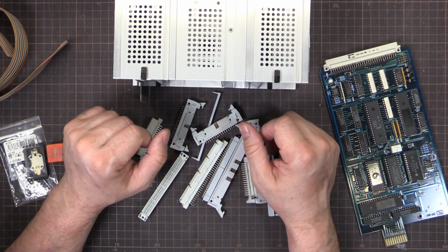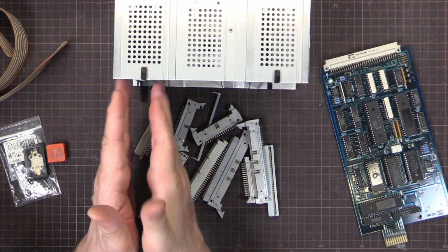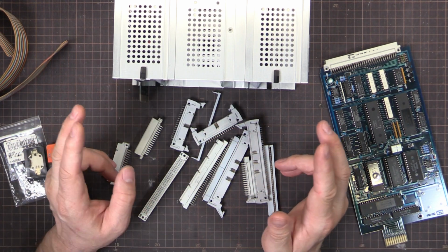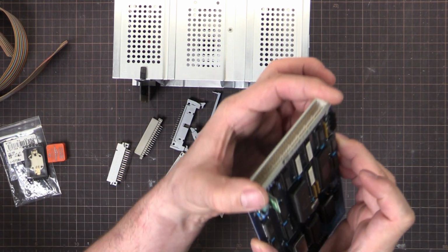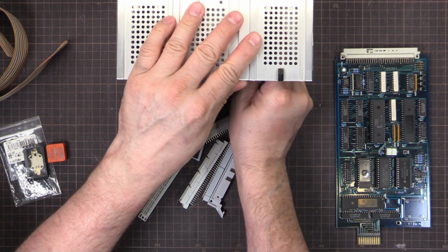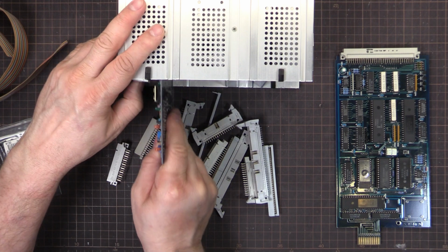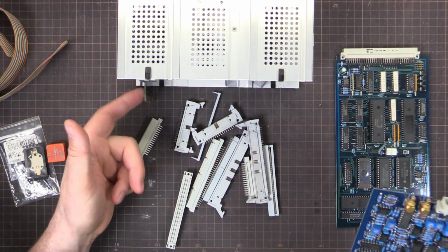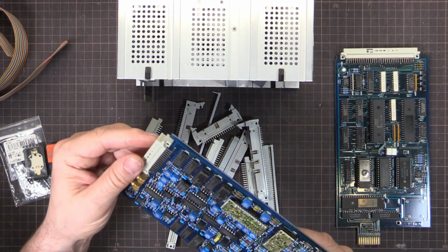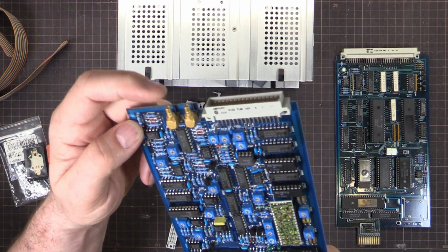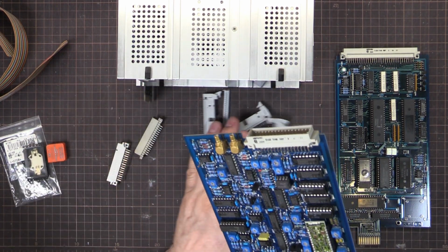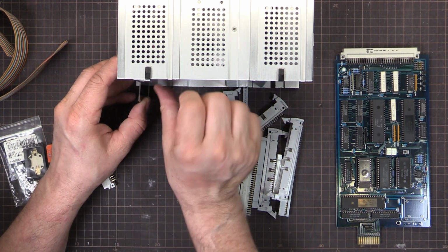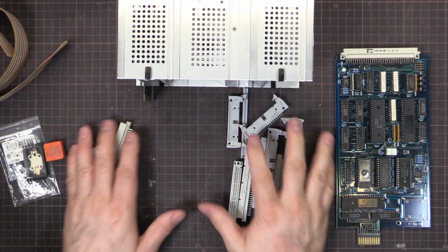To calibrate this thing, we need to make extender cables because the cards kind of slide in and you can't get into the inner card because the outer card's in the way on both sides. So you need two extender cables, one for the big connector, that big one there, and one for this card, which is a small connector. Or this card, one of the two cards. I've got to double check because I might need to make extensions for these coax cables. They're just an SMB connector, nothing too fancy there. I'll just get some off eBay for a couple of bucks shipped from China. That's not a worry. I'll see if I need that. I'm not sure yet.